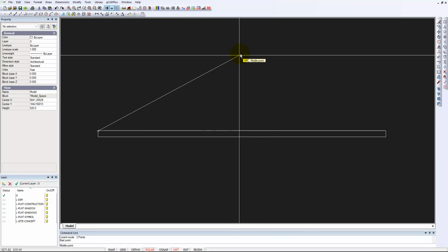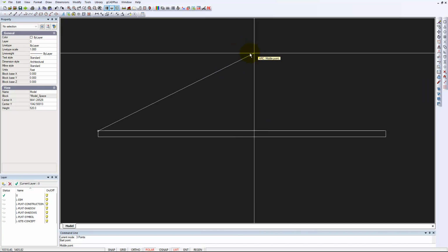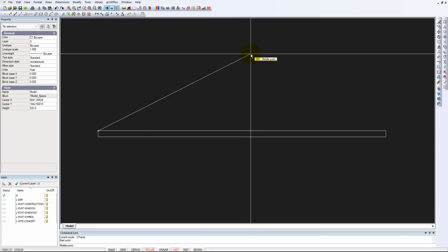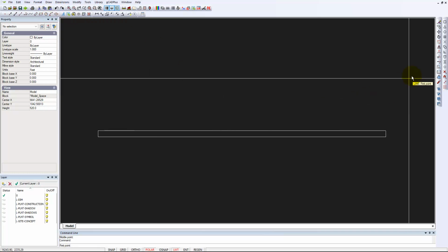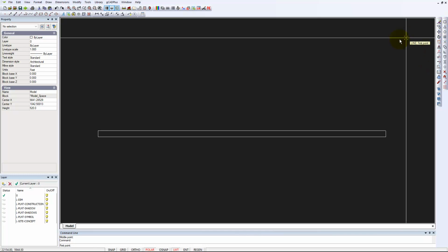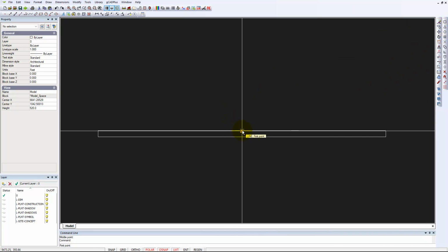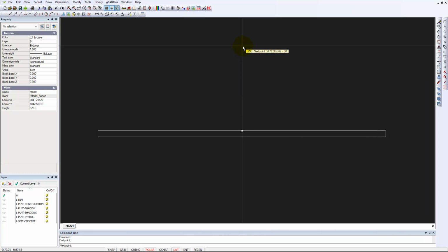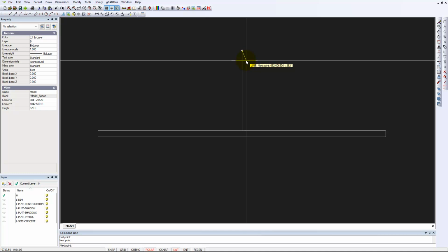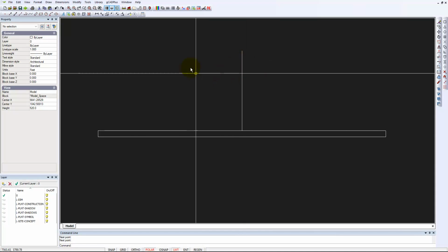So we don't have a middle point there, and if I just do it by eye, it's going to become a little ugly. So what I will do is draw a little, effectively a construction line from, I'll use another snap or OSnap and pick up the middle of that line with ortho on. I can go approximately out for the distance of the arc to form the garden bed.